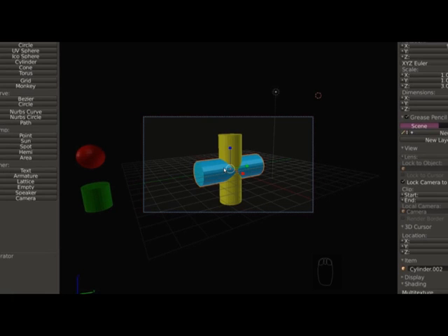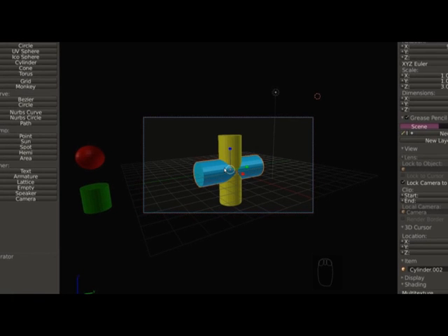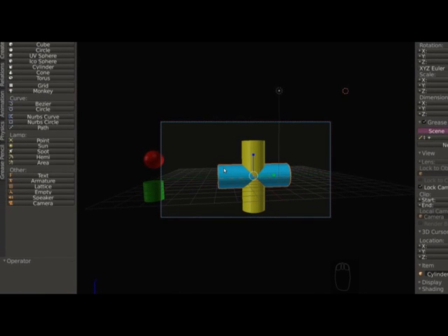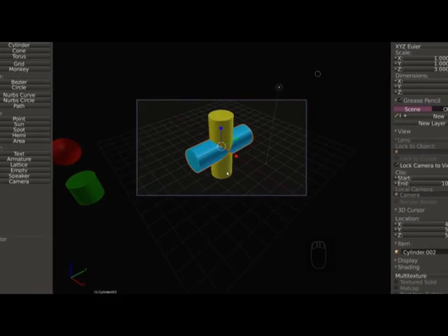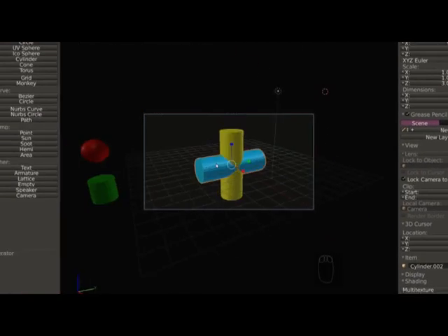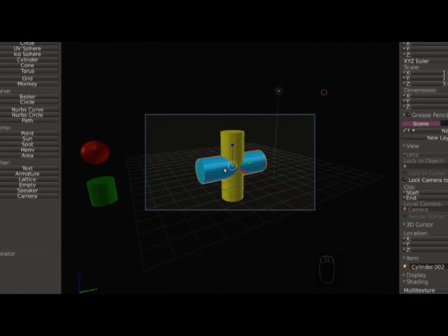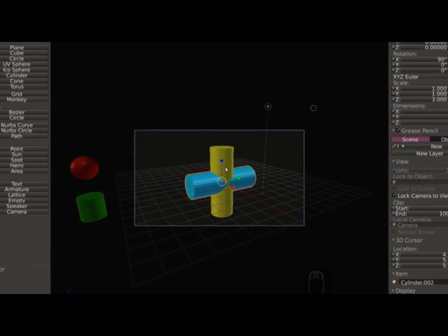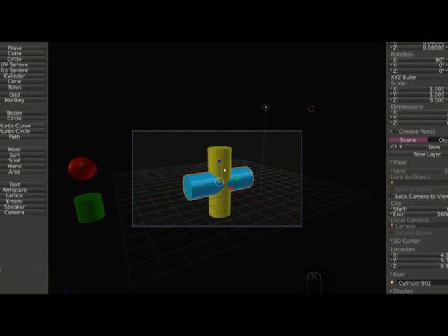Now what I'll do is middle mouse button, hold it down, and I'll drag it to the left to rotate my cylinder around so we can see it. You can see what it looks like. You can actually see it's a perfect intersection from all points of view, so it's quite precise. All right, now all we have to do is apply a modifier, our good old Boolean modifiers.